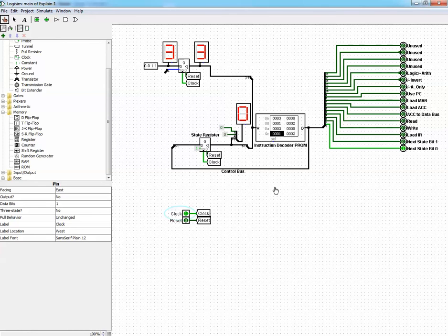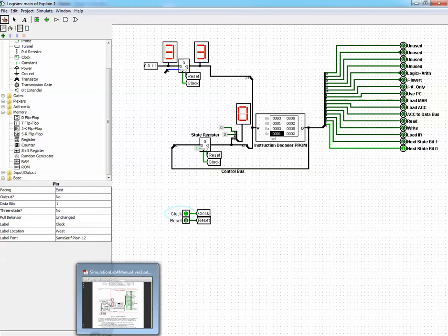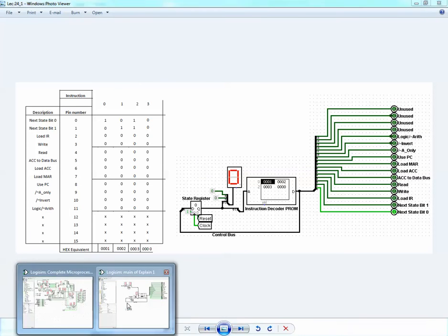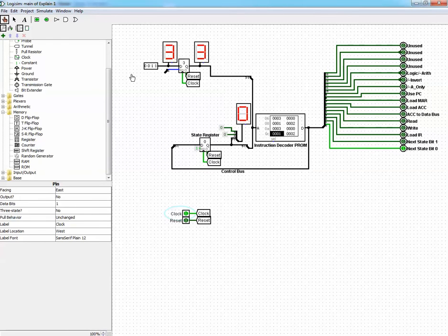Okay, so remember that this corresponds to what? Here, this value corresponds to the 4 most significant bits that are fed to this address, while these 2 bits correspond to the 2 least significant bits of this address. Remember that this enable is always enabled. We did not connect it to anything, so it's by default assumed to be enabled.